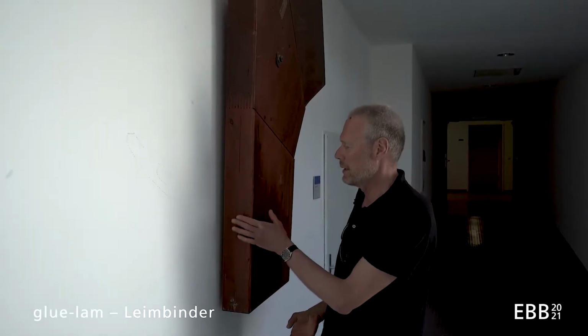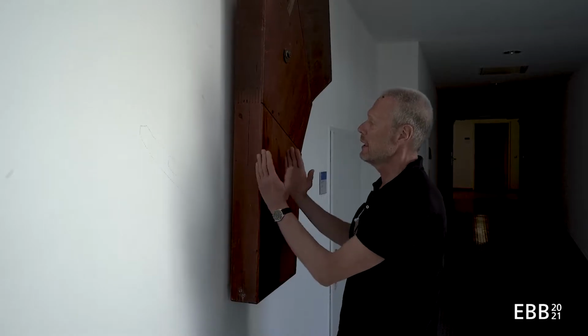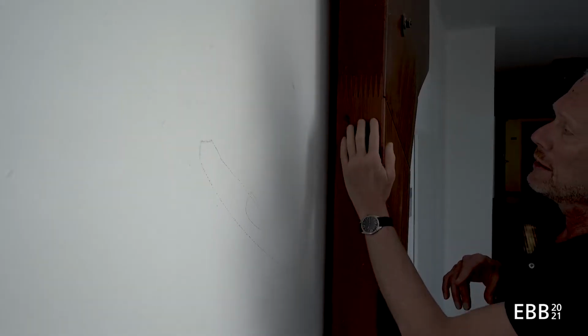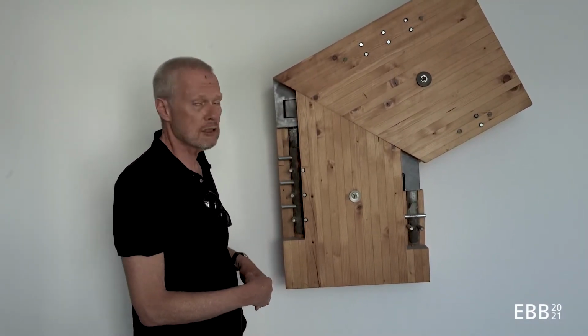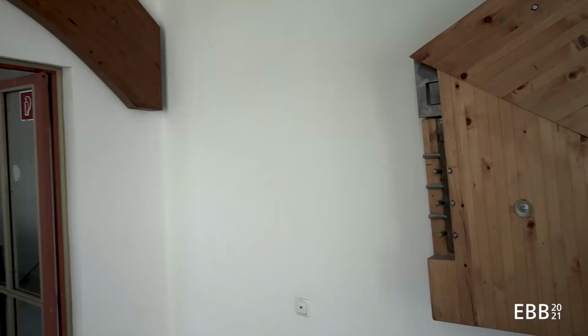So a rather typical wood-derived product is glue lam, where you cut the wood into boards and then you glue them together. And you can create rather infinite sections by finger jointing one piece to the other. Wood can also be combined with metal connectors, as can be seen in this angle joint here. And on the other side, we have a collection of different connectors that are used in wood construction.